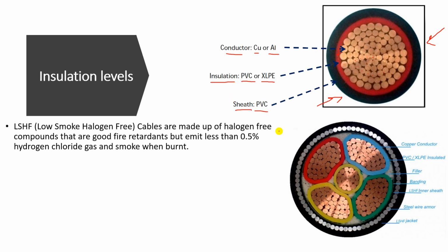Now let's look at these cables. This one, for example, is a multi-core cable. We will understand in the next lesson the classification of cables according to cores. However, this one is called a multi-core cable because it has more than one core. As you can see, we have this red one, the blue one, and green, yellow, and the earthing one. So we have five. This is called the 5-core cable: the 3 phases, neutral, and earth.